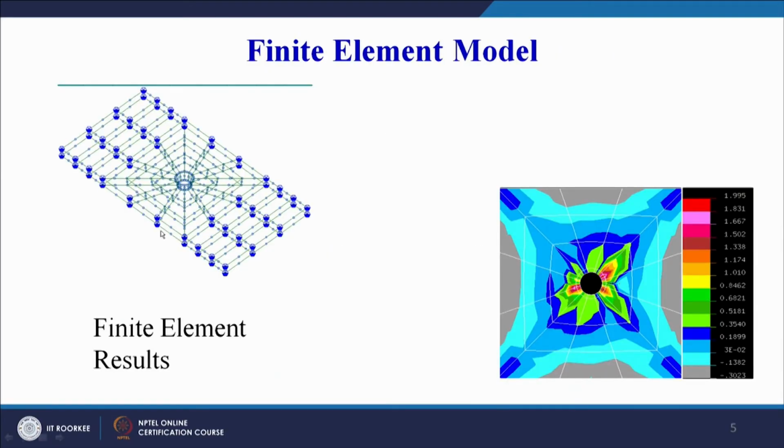Then we can see these are the boundary conditions. This is the plate in which we want to make a hole. In many cases we can assume that there is a pre-hole that is existing and we can enlarge that hole using the drill. And here we can see this is the boundary condition which shows that the plate or the composite laminate has been fixed in this area.